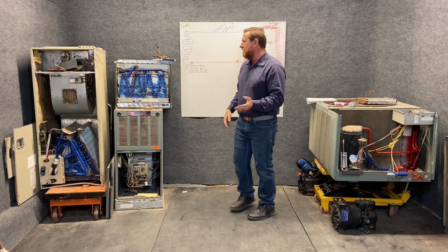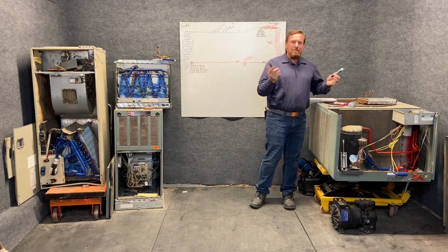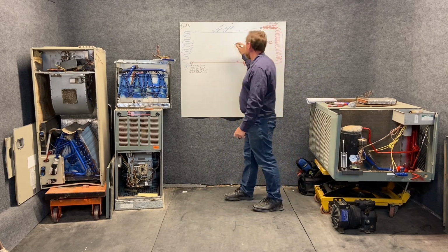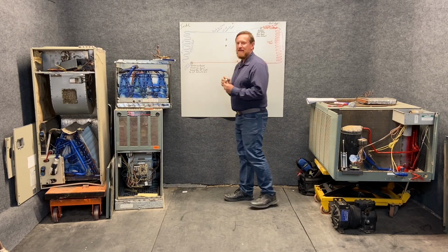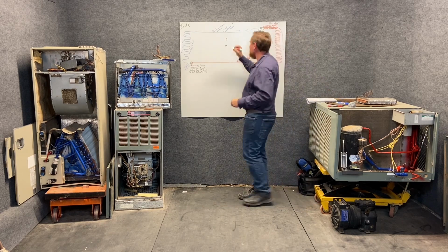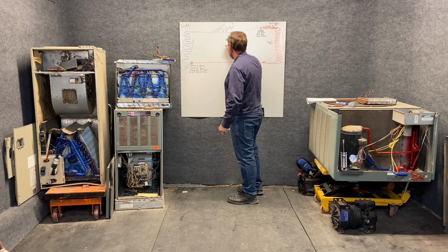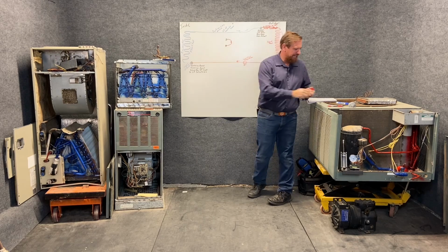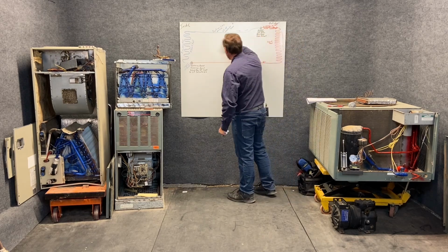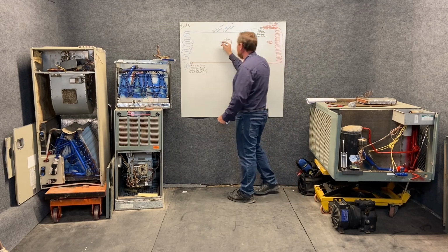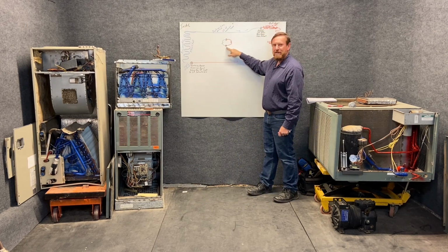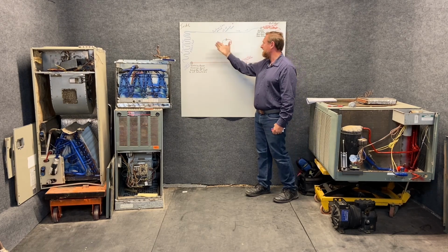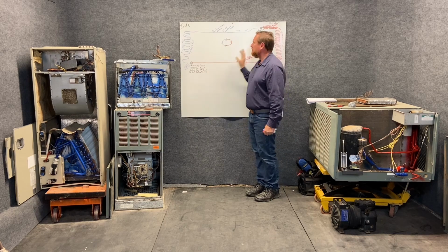Redraw this however many times it takes. Now, if you're in another school, people draw this all different kinds. When I went to school, we learned it as a compressor, and the metering device was below it. And then we had, as a circle, our condensing side, and on the other side, our low pressure to evaporator side. And it's still the same cycle. We have our compressor, condensing coil, metering device, low pressure, evaporator, back to the compressor. It's still a cycle, but it never really said how everything was in the system.